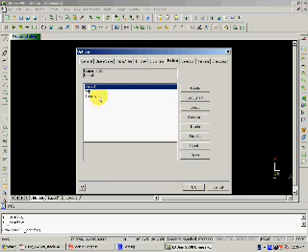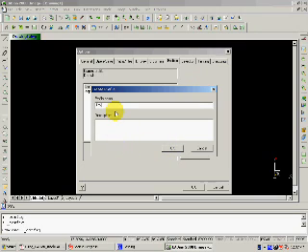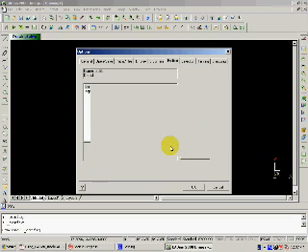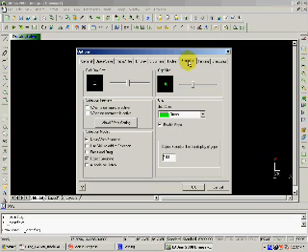Further, what we suggest you do is set up some templates for yourself that you can work with. Let's just delete the older one, just create a new one for training. Now, this is used for different users on the same computer, or if you have different styles you want to apply and different things showing. It's a quick way of getting your icon bars where you want them for different options. If you're doing dimensioning, for example, you want to keep the dimensioning toolbar available. It takes a minute or so to run it and set up for itself.